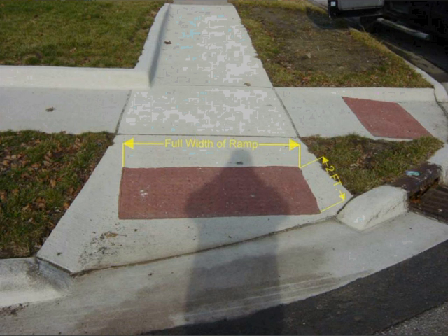Detectable warning should be the full width of the ramp. If you've got a 4-foot ramp, it should be 4 feet, 5 feet should be 5, and 10 feet should be 10. That doesn't include any flares on the sides or the curb on the side of the ramp. The depth in the direction of travel should be 2 feet, and that's based on research done nationally that tells us that with 2 feet, it's less likely that someone's going to overstep the detectable warning.